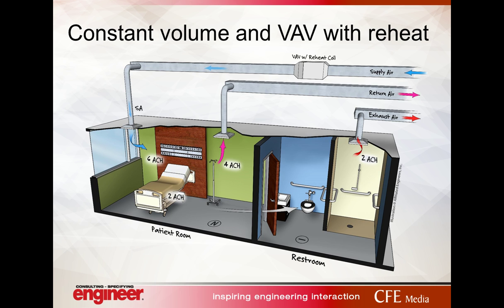First, we'll talk about our VAV and constant volume systems, which are probably the most common that you'll run into. I'll use the same graphic to talk about both. In a VAV system, you send air into the room and it varies depending on load. The minimum will be the minimum code required air changes probably coming from ASHRAE 170, and the maximum would be whatever the load in your room demands. If you have a lot of glass, if you have a lot of occupants, the actual ventilation quantity may be higher than the code minimum, but it would fluctuate between those during the day as the load changes or during seasons as the load changes. If the load drops below the minimum requirement, then a reheat coil, electric or hot water reheat coil, will kick on and modulate the load from there. And all of that air, or a significant portion of that air, gets returned back to the air handling unit, filtered, cooled back down, and recycled.